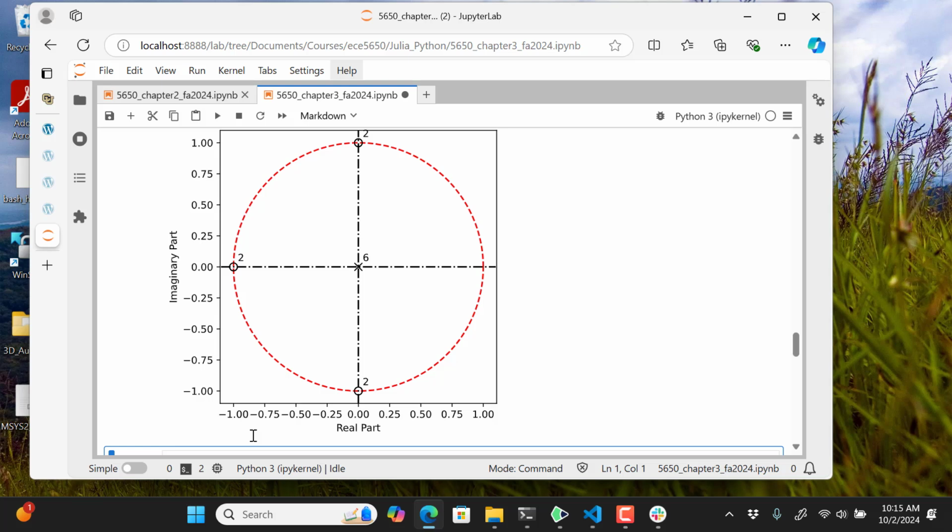And what it's going to be is a sixth-order system, and you can see that in this case the roots are repeated, and it's because of the convolution theorem, actually. We're taking a rectangle and cascading it with another impulse response that's a rectangle, and in the z-domain that will be the product of those z-transforms, which will be repeated roots then. If we have a root at one location, because it's cascaded with the same system, it will get repeated, and that's why the 2's are on there. And you'll be exploring that in one of the homework problems, or you do explore that. Is that interesting, or is it too much to absorb?